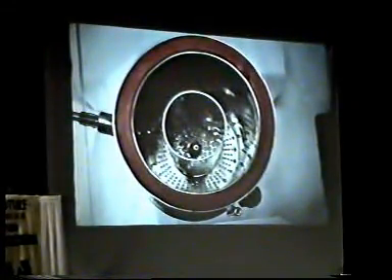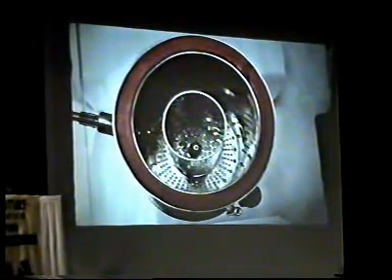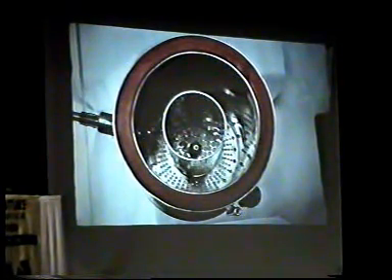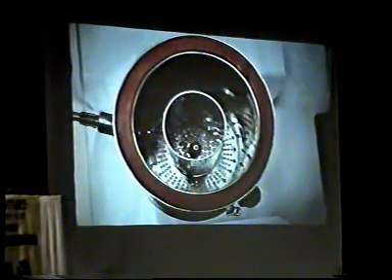This is a shot taken while coating is on. This is a roto process granulation, enteric coating of diclofenac sodium is in place with tangential spray. You can see the pellets rotating on the rotating disc. The next slide, please. This is the bottom top shot of the bottom product container in a booster chamber. You can see the air distribution plate, the booster chamber, and the bottom nozzle in place. The next slide, please.